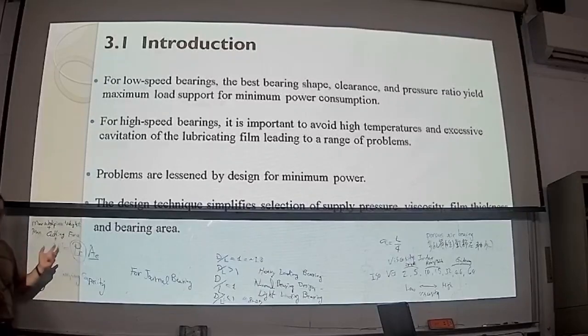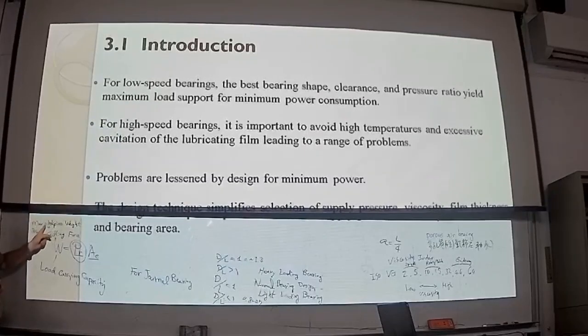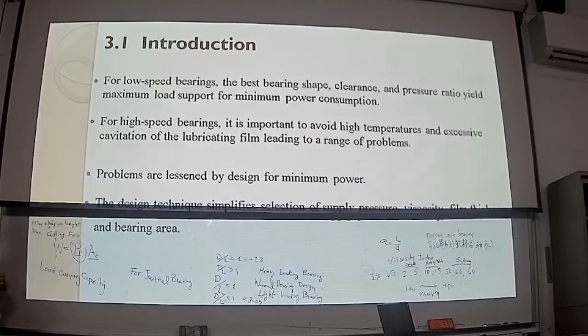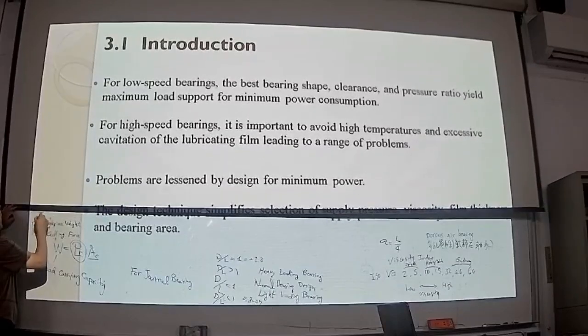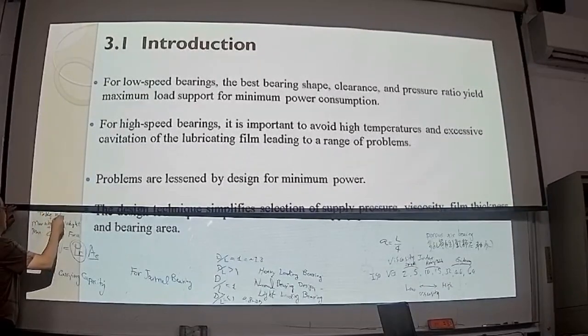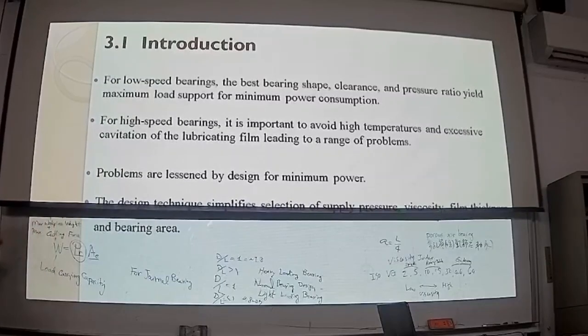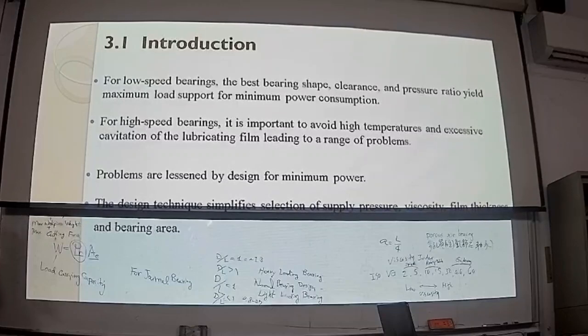For example, if you have four bearing pads in your slide table, then the area of one bearing times 4 must equal the total load. So slide table weight plus the maximum workpiece weight plus the maximum cutting force will give you the overall load capacity.